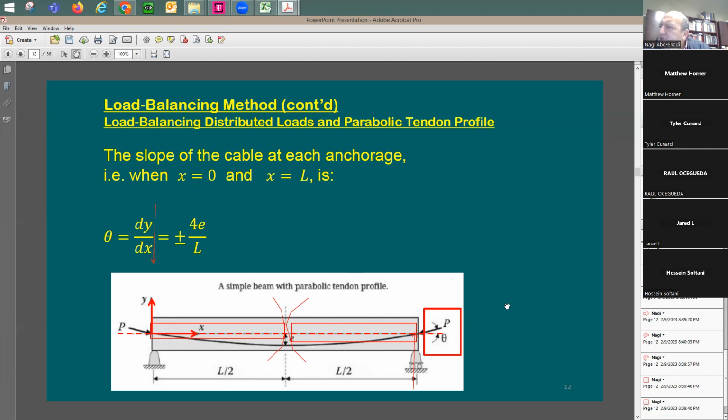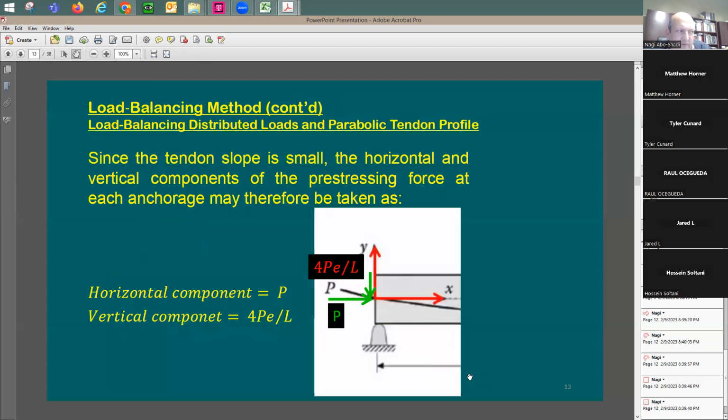This is going to be now the question to you guys. What is this pre-stressing doing? Is this pushing the beam up from the support? Is it going to be pushing it down? It's a question to you. How do you feel about the mechanism of this or the performance of this? Down. It's going to be pushing down. This means the pre-stressed beam itself, after they put the pre-stressing, is going to be pushing down the support.